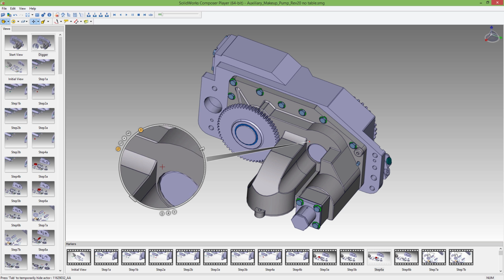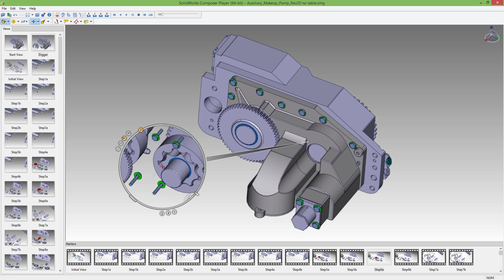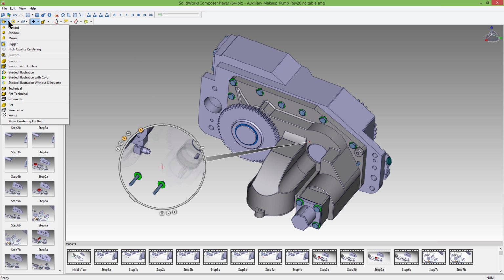Upper right allows you to adjust the percentage of the particular item that you're on. I'm currently on a zoom, so that allows me to zoom in and out of the model. One of the useful ones is the X-ray. It allows you to peel away the inside of the model, so you can actually see the inside of it, based off of where the percentage is at. So again, spacebar or the digger tool in the upper right there.